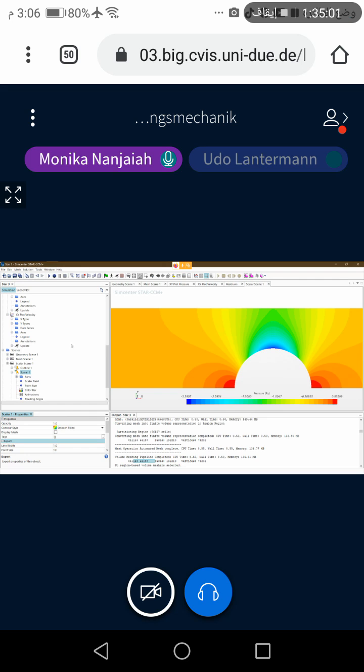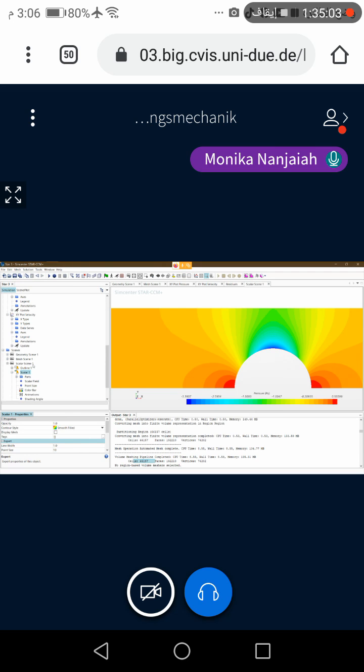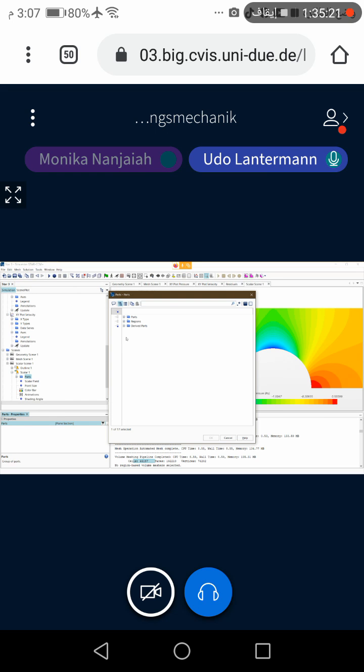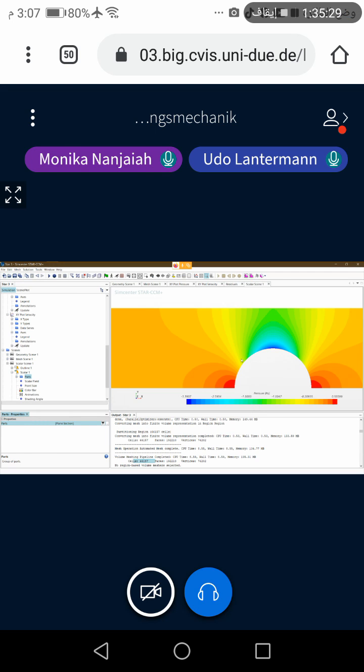Could you please repeat how do I get this scalars? I created a scalar scene, and then you have to include your plane section in the parts. So open the scalar. Yeah. And then click on parts. Yes. And then below, you have to choose your derived parts and then plane section. Okay. And then it should appear. Yes. But you also have to select your scalar field. There I choose the pressure. I choose selecting that. Thank you.